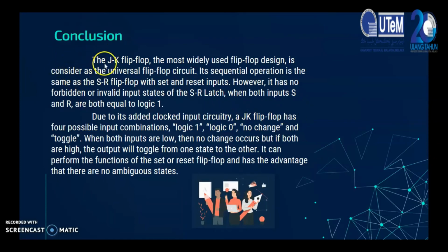The conclusion is that the JK flip-flop is the most widely used flip-flop design. It's considered the universal flip-flop circuit. Its sequential operation is the same as the SR flip-flop with set and reset inputs. However, it has no forbidden or invalid input state like the SR latch when both inputs S and R are equal to logic 1.